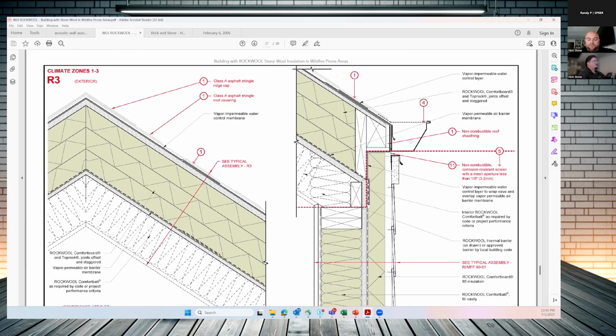And I've dealt with Oklahoma in the past, and they see the changes because they're in climate zone 4. Well, 3 for most of Oklahoma, but they want to get away from continuous insulation. And I understand why, because the builders aren't ready for this yet. However, you're stuck with either a high density fiberglass to get R15, which yours will also do, R15 on a 3.5-inch cavity. But open cell foam can only do 13.